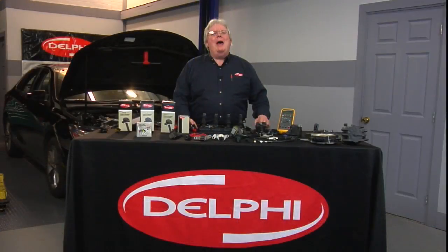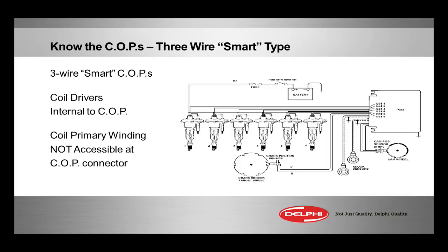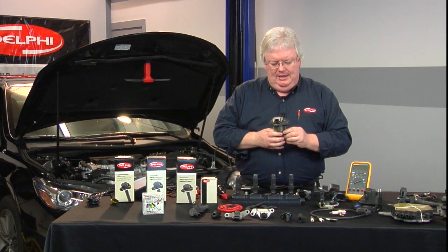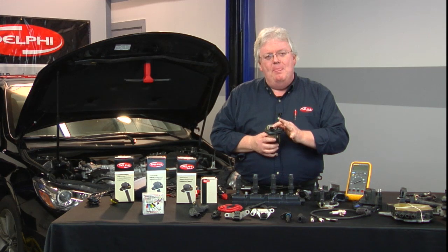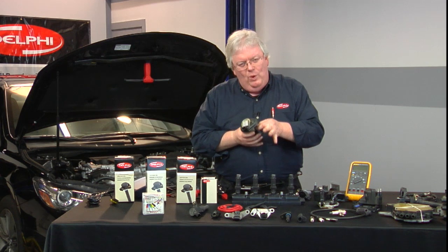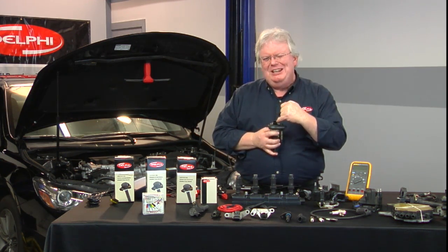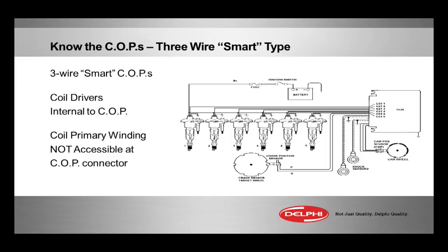Wrapping some of this bench work up with what we see here on our screen, 3 wire, I'll call it smart, early GM smart Coil-On-Plugs. If you recognize that particular shape of the coil, that's that Delphi 3 wire 4200 inline 6, that Vortec engine. This heat sink is common electrically, 0.1 ohms, with the mounting bolt. But the ground is a little different resistance level than this ground right here. So basically, like I said in the hands-on portion, you want to make sure that you absolutely know what you can do on the bench, otherwise more than 2 wires, you're not going to do bench testing.